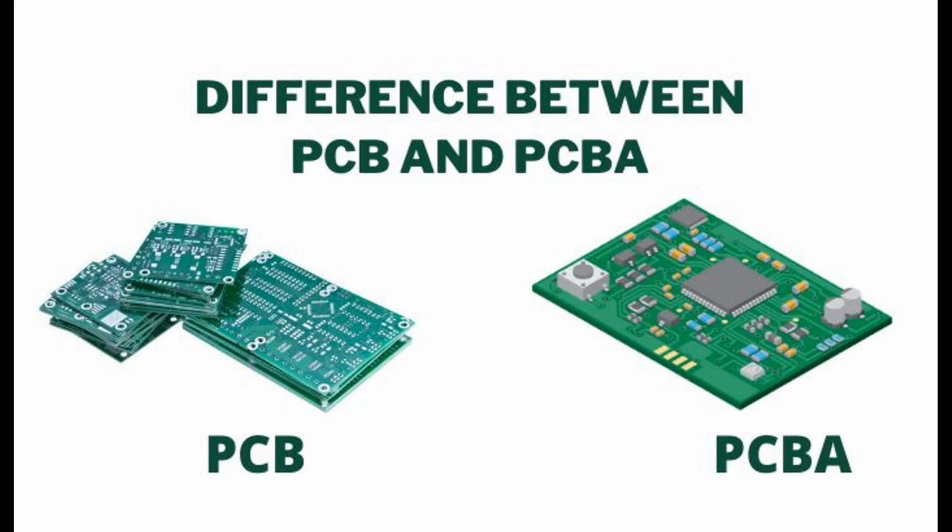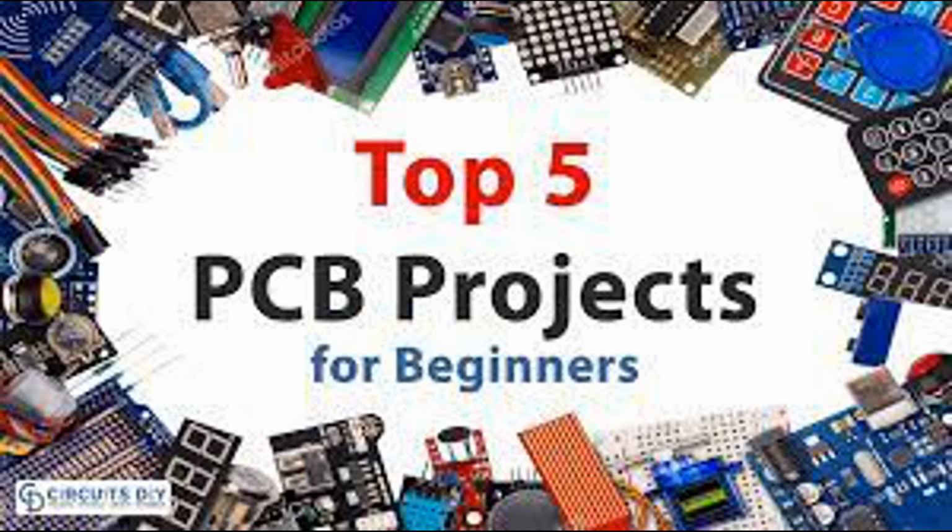Design considerations: the width, thickness, and spacing of traces are crucial design parameters. These parameters are chosen based on the current carrying capacity, impedance requirements, and signal integrity considerations of the PCB. Wider traces can carry more current, while narrower traces may be used for signal lines.